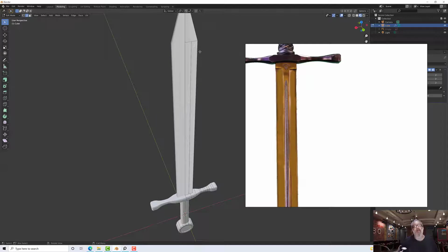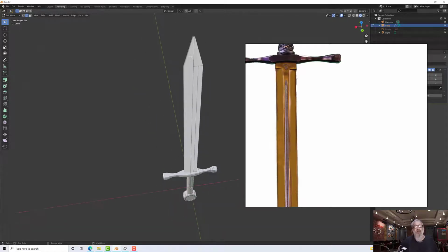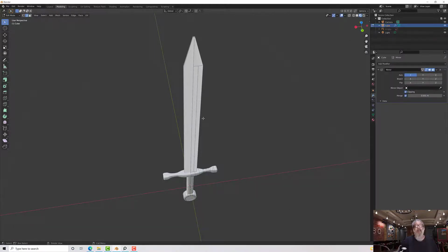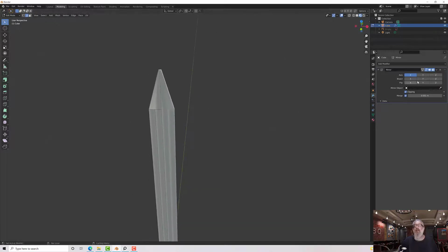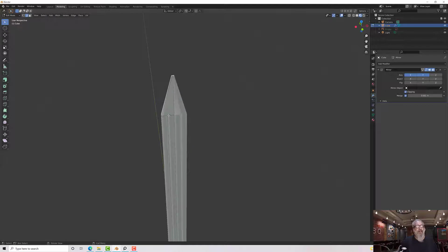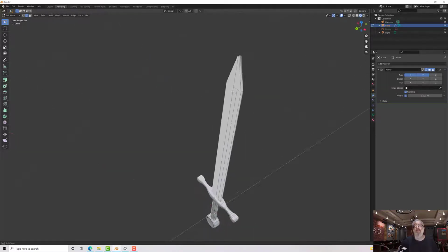And this is an argument for using mirror on Z as well, or Y rather. So let me just minimize that. So let me undo, and I'm going to turn mirror on Y, and now we use K again. Whoops, that's H. Point there, go up my sword model, click to put a point down, enter to finish, and that should go on both sides.